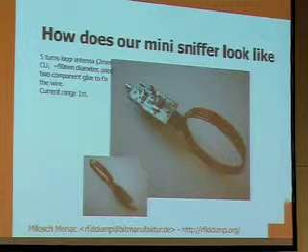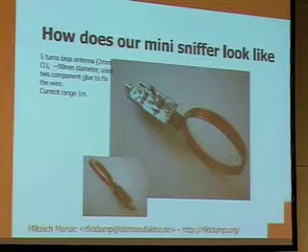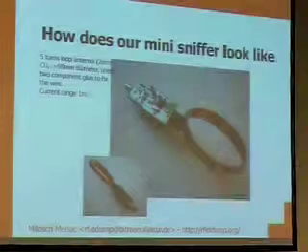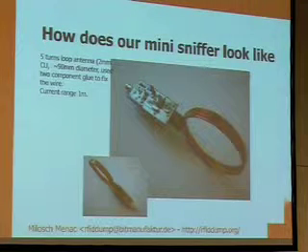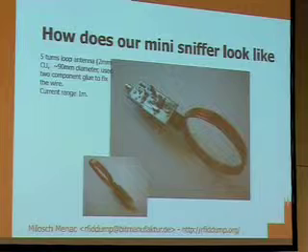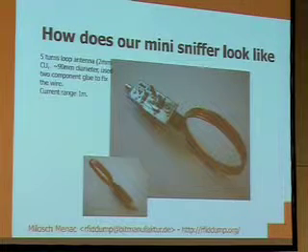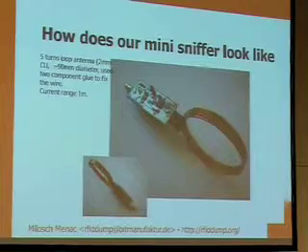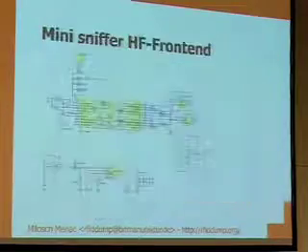Basically, you see the chip that does the down mixing. You have the crystal that creates the 3.68 down mixing frequency, and in the lower picture you see a 9-volt battery and a linear regulator which creates the 5-volt power supply, and you have a high-speed op amp that buffers the signal, so you can do everything you want with the resulting signal.